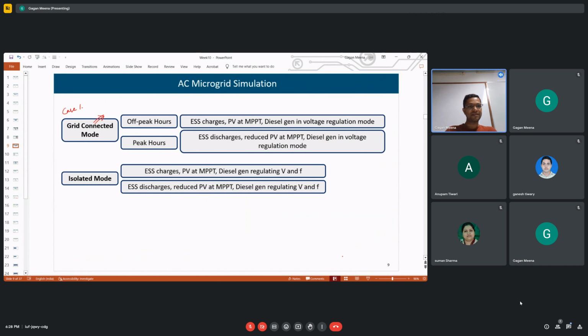I'm not remembering right now, but the IEEE standard has it. Similarly, a voltage swell is a temporary increase in the RMS value of the voltage. Here you can see the increase in voltage level, then after some time it becomes normal. And this is an interruption. The voltage becomes zero for a few cycles, so there will be an interruption of supply.